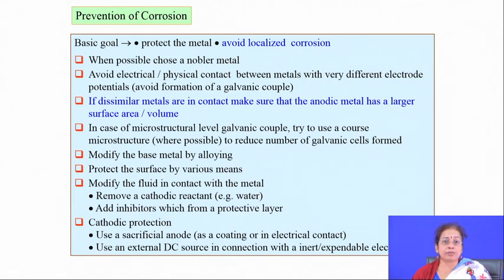So, these are the different precautionary measures you must take in order to get rid of the aqueous corrosion problem. If you talk about the high temperature oxidation problem, as I mentioned, you have to apply certain alloying elements on the surface by the process of surface alloying, either by pack cementation based surface alloying or by laser surface alloying, so that whatever surface you are modifying is protective in that particular environment.